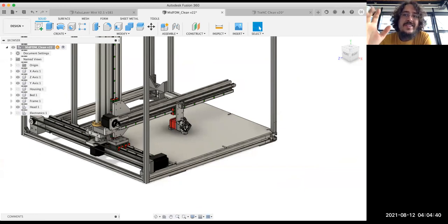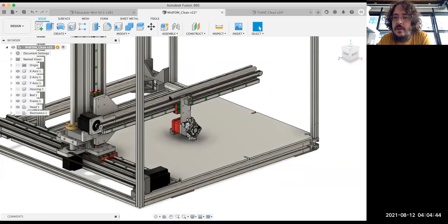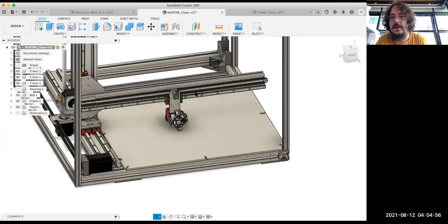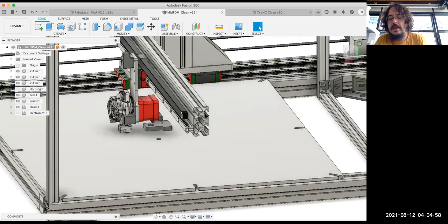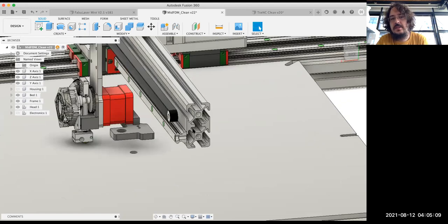What we have also tried, just quickly, was to reduce the weight of this axis, to make it way lighter. And guys, this resulted in much worse results. So the heavier this axis is, the better, and we thought about this because this profile is a 30 by 60. It's able to give smoother oscillations than the small one, which is more nervous and gives more shakiness or something like that.